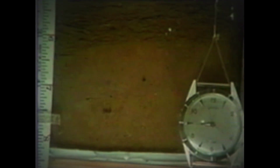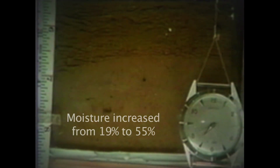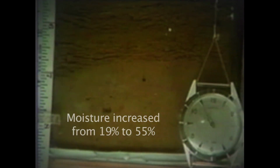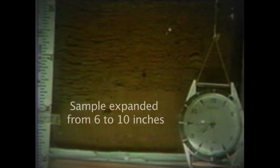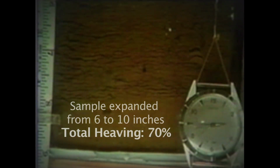The camera was repositioned as the frost front approached the bottom of the soil sample. The moisture content increased from 19% to 55%. The heaving observed was entirely due to the accumulation and expansion of the water in the soil as it was transformed into ice. The originally 6-inch high soil sample grew to 10 inches, a total heaving of almost 70% of the sample's initial height. The lenses in this experiment were fairly small and uniform in size.